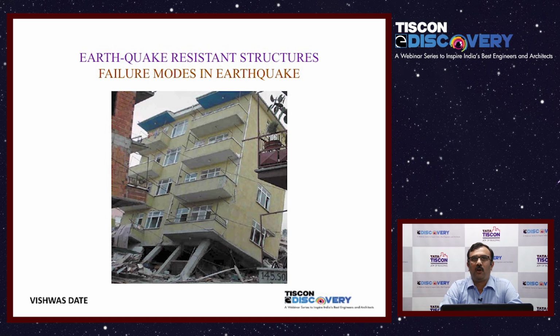That's where we talked about earlier, foundation systems. Now, this soil, we don't know what characters it was, but basically this happened because of soil upheaval or soil liquefaction. So soil actually gave away completely and the building tilted as a whole. The total building tilted and collapsed. So that's why we need to have a better understanding of our soil foundation strata.